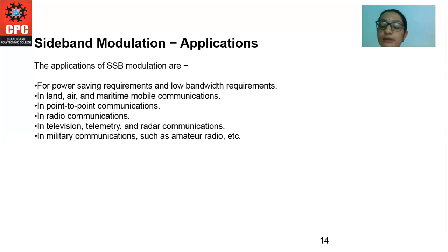Second, it is very expensive to design a tunable receiver oscillator with very high frequency stability, due to the use of frequency synthesizers. That's why SSB is not used for broadcasting purposes.